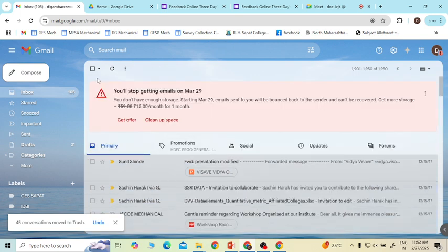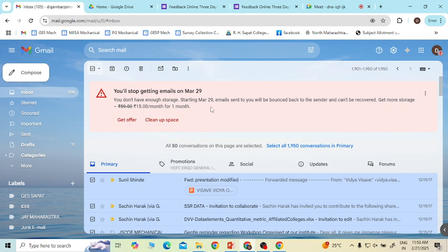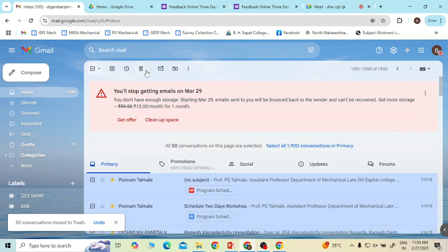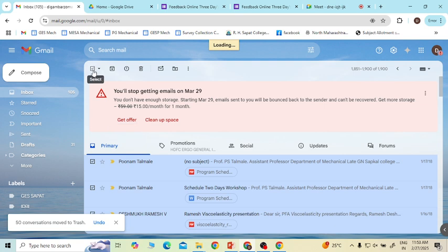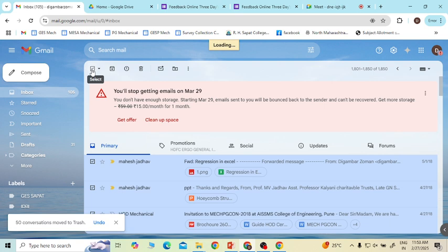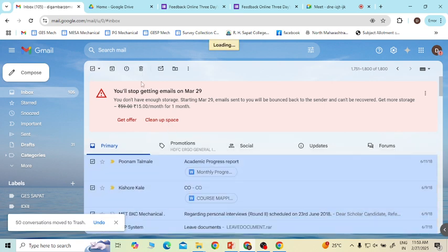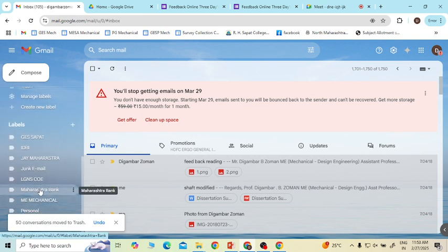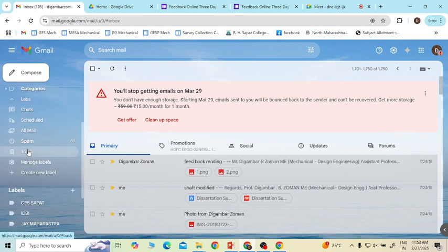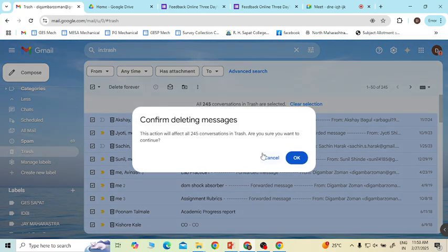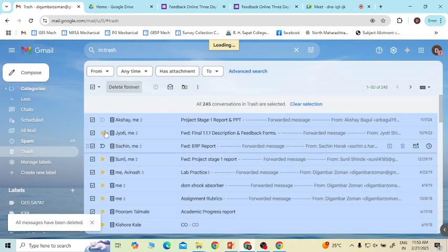So this is for stereolithography. Here you can see a laser beam, and this is the tank wherein there will be resin. The Z direction will be controlled by this, and the XY will be controlled by this laser. You have to focus this laser. The XY provides the shape and size of that particular layer. Depending on whatever is exposed on this table, that will be cured by the laser beam.